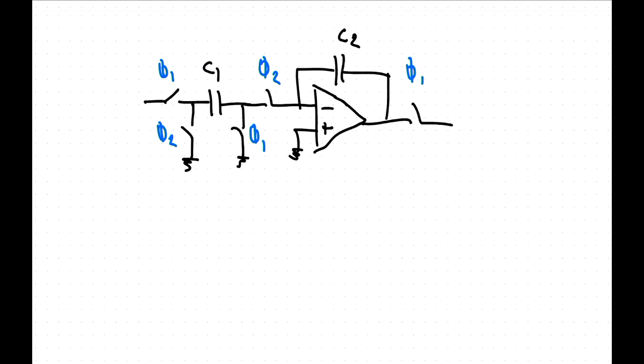So with this switch arrangement, you can see in clock phase 1 we have current flowing into the capacitor down to ground, so we're going to have the capacitor charged up, positive sign that way there. And in clock phase 2, we've got virtual ground here and ground here, so we're going to discharge it, but now the current has to flow into the left. So we're going to charge up the capacitor. So it's going to be the same transfer function, except that the charge now in C2 flows in the other direction.